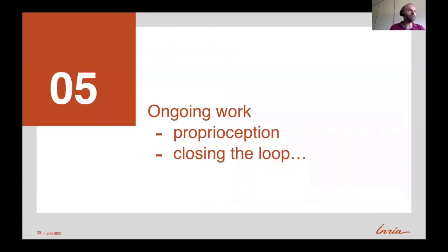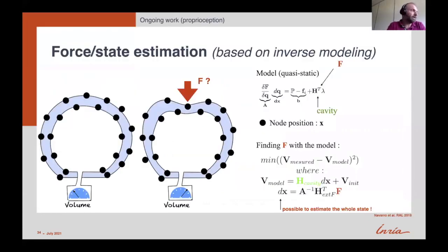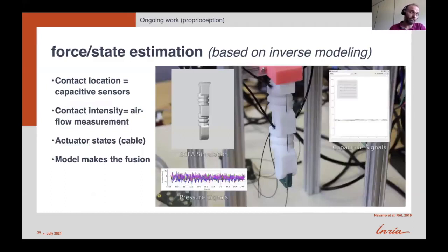It's only simulation. It has not been demonstrated in the real world. What we would like to do in the future is to have also a force and state estimation, also based on inverse modeling. So we have done that recently, thanks to an adaptation of our inverse model. Here we add a new constraint again, which measures, for instance, the change of volume inside the cavity. And thanks to this change of volume, we can estimate by the inverse the force applied on the robot.